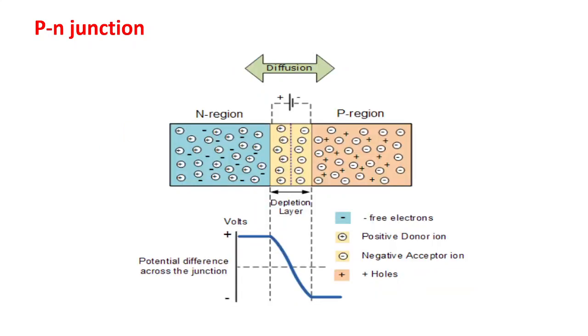In the N type region, there are some positive donor ions, as we say when we make N type materials, and there are some negative ions in the P type materials. The N type material had free electrons and the P type material had free holes. These move toward each other and create a depletion region. This is the state when we just manufacture the material in the factory.